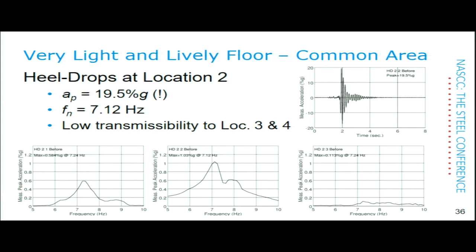That might be the highest one I've ever seen. That's pretty huge. You can really feel that. Now, the natural frequency was 7.12 hertz, as you see in the heel drop spectrum at the bottom middle there, at location number 2. And we have 7.12 hertz as the natural frequency.